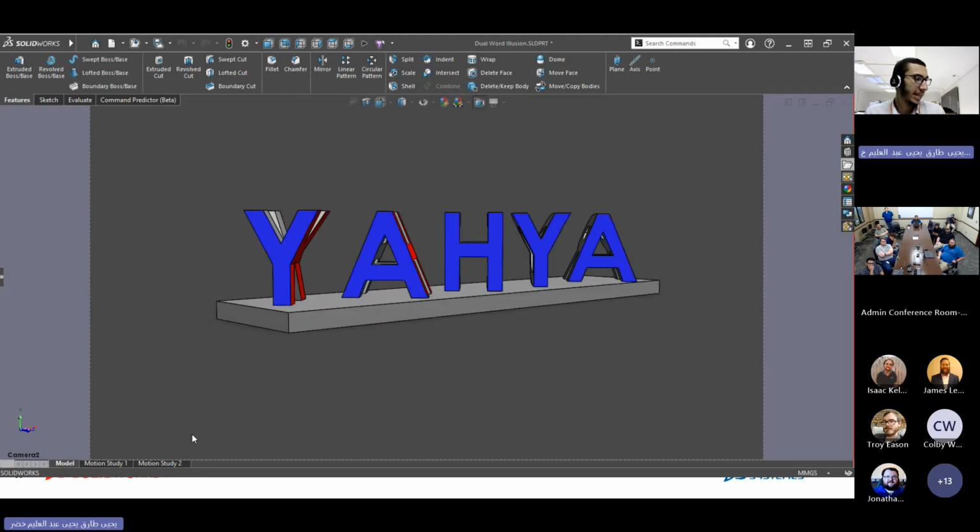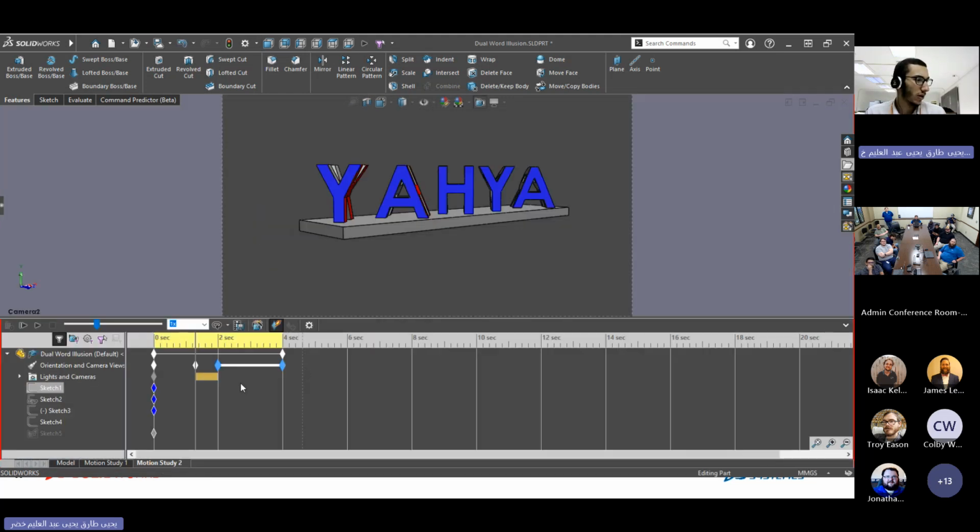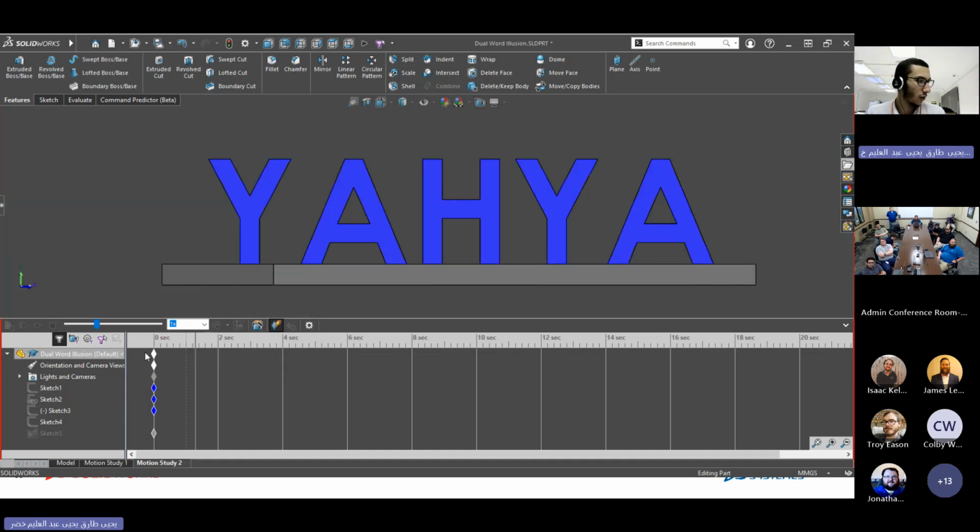And now let's revisit our motion study. So what I want to do right now is obviously delete all of this. Go all the way to the 0-second mark. And I can notice that it's still using the first view that I had from earlier. And I want it to change to the camera view. Okay, so you can get the camera view from over here.